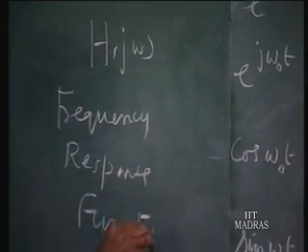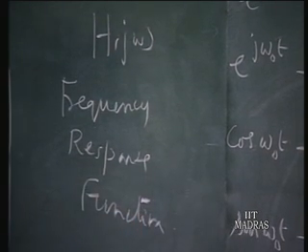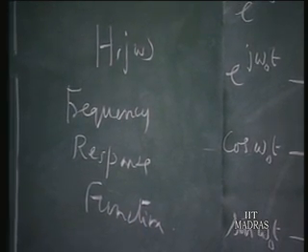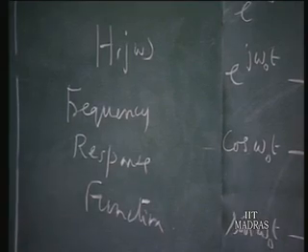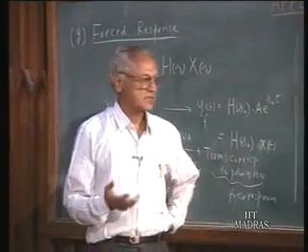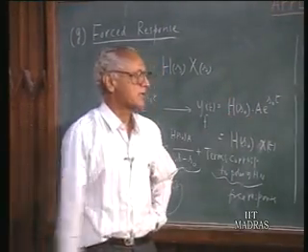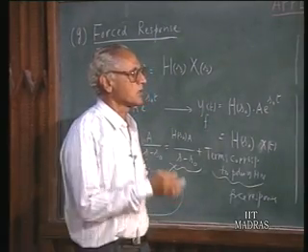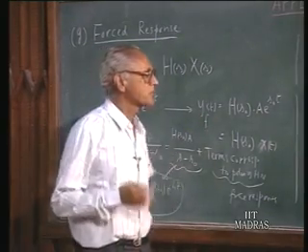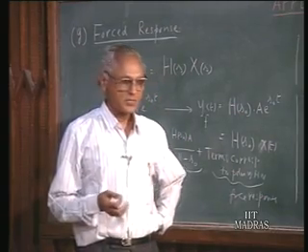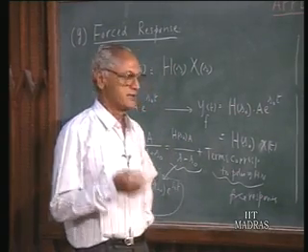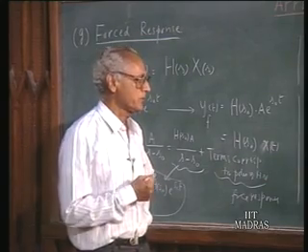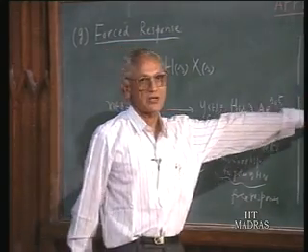Which we had used in steady state sinusoidal analysis, circuit analysis. After all, H of j omega is something like your impedance Z, Y, and all related to H of j omega. Z is a function of omega, H of j omega is a function of omega. So impedance is the ratio of voltage to current. So if you take the voltage, the response quantity, and the current as the input quantity, the system function corresponding to that is Z. Normally what we talk about, Z is a system function in this context.